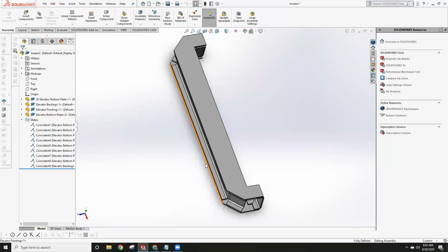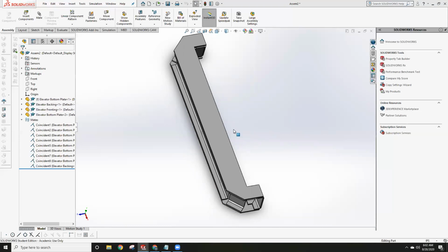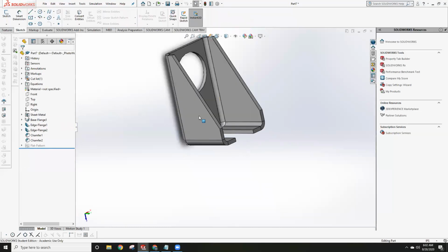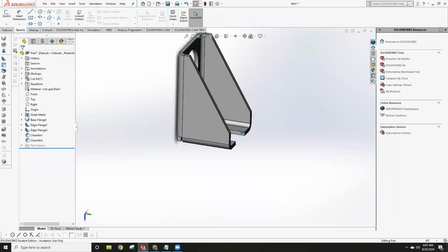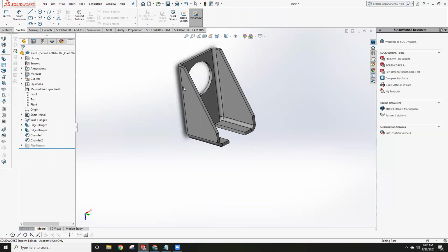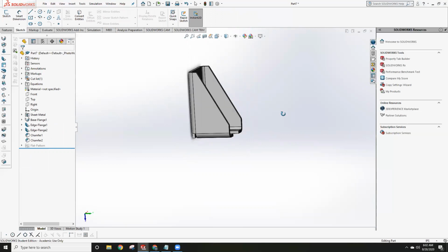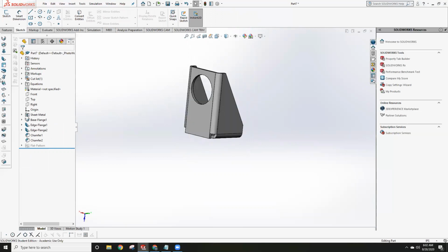Use a hole pattern instead of aligning your holes. Make your parts to where, again, you look for how the forces are going to be coming on it, and then just adapt it to be better suited for it, and be sturdier. And then, yeah, don't use the hem tool. That's about it.